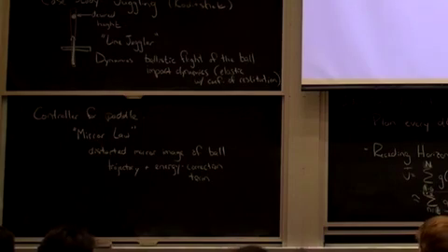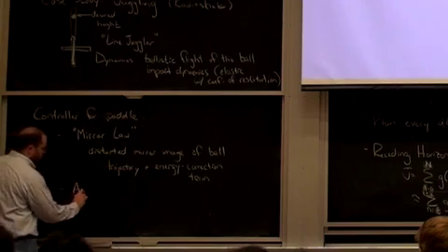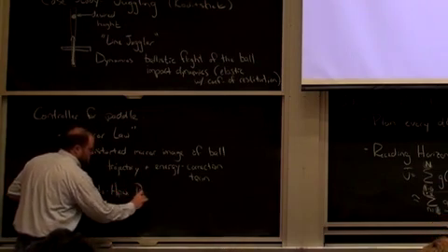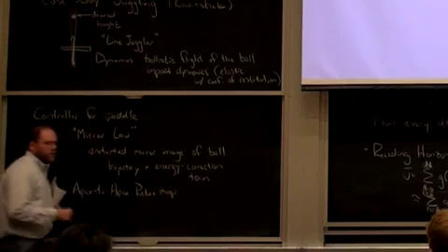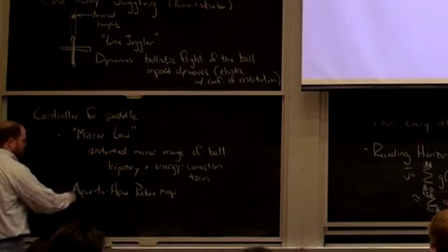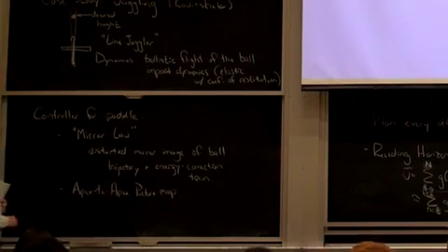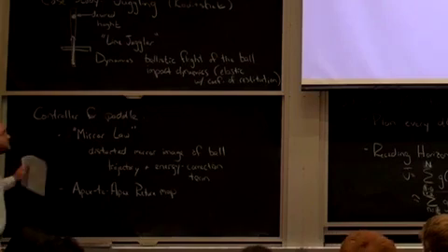Okay, how do they prove it's globally stable? They do an apex to apex return map, the same way we did for the hopping models and all the other models. These guys were pushing the unimodal maps and getting some global stability results out of that. That's why I think that they had a global result. So it's actually exactly like a hopping robot, just the ball's moving instead of the robot.